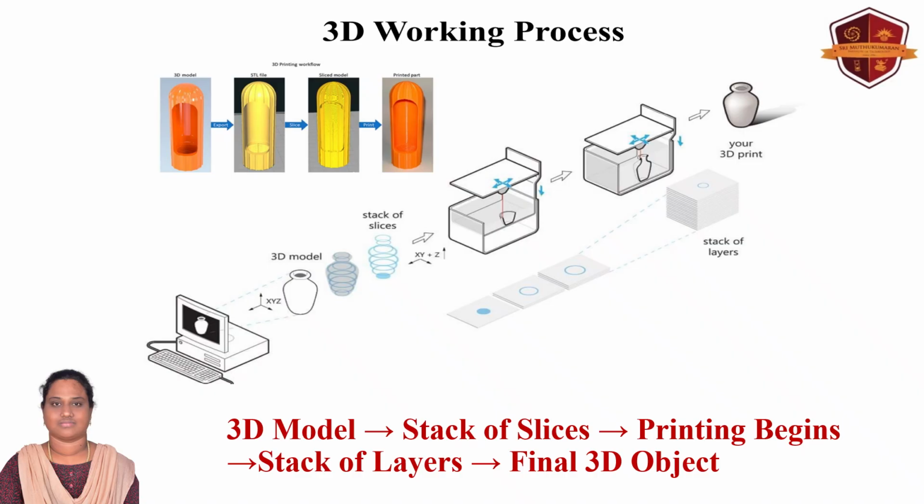I summarize. The step 1 is creating a 3D model. Here the object is designed using a CAD software and the model is exported as an STL file. Then it is loaded into slicer software. It sets parameters and the output of the sliced model is G-code.